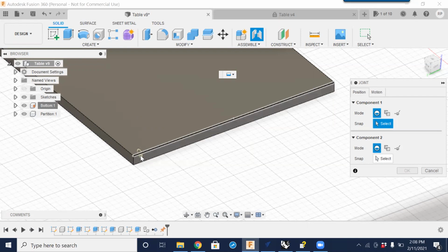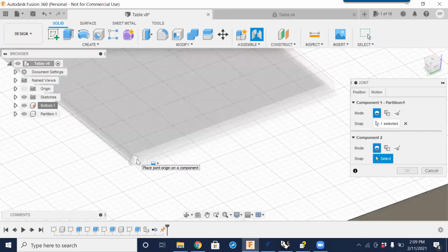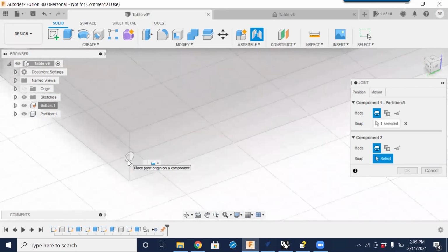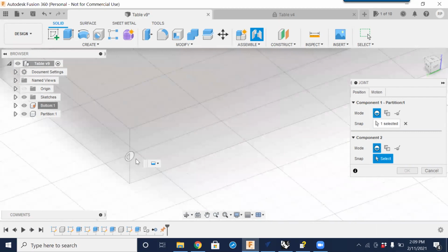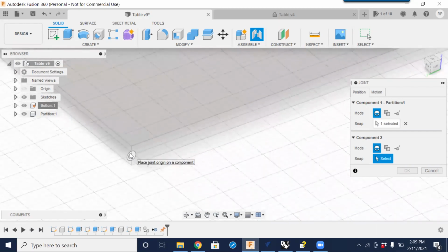And I will mention, as you come around here and select it, it's sometimes difficult to not have that bounce around. So once you get the face selected that you want to have this applied to, hold the Control key down. And that means that no matter where the mouse is, it's only going to be that face. So notice I am selecting like the midpoint of the bottom of that face. So just zoom in and we can see where that is located.